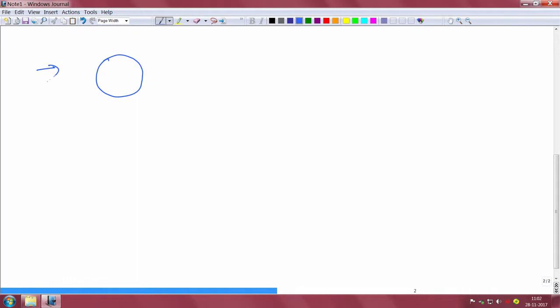Okay. So, if you take a cylinder or a sphere in a turbulent flow field, and you start to look at the wake region, you will find that the wake will have very large eddies. Eddies means rotating flow components. You will have slightly smaller eddies, you will have very fine eddies. You will have lots of these kind of structures.